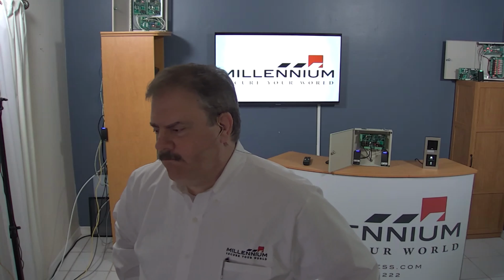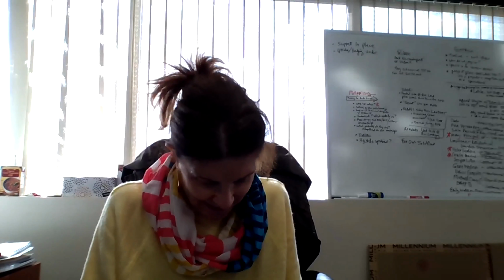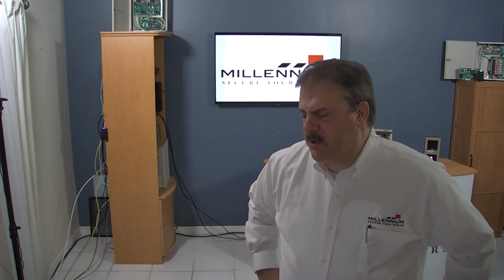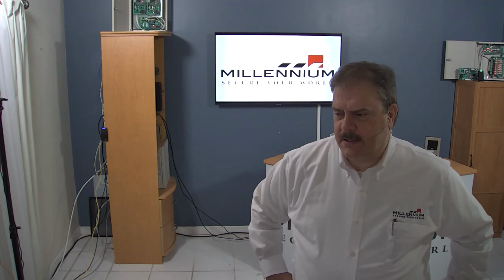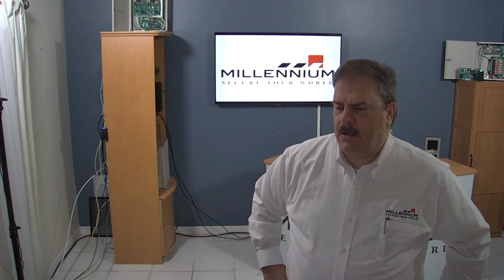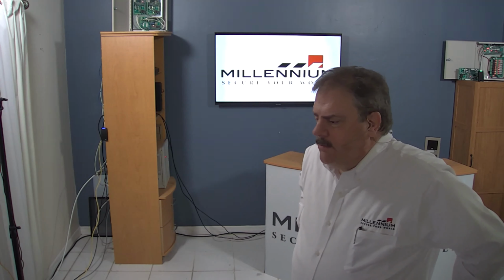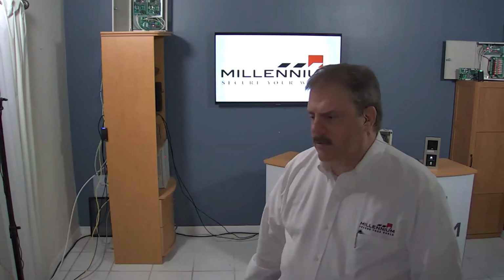Yeah, amen. Plus the battery backup, you've got to consider how you're going to back up power in case of power loss. It's harder to do on a PoE switch than just the 12 volt, which is already built in. Yeah, well, yes, agreed. But in his specific need, I think we do have a solution for it. I love PoE as well, but there are some downsides to it. Absolutely. The PoE would be great just for enhanced site control, but when you start powering other stuff off it, like a net DCD with 2 readers or something, you could start running into problems. Exactly.